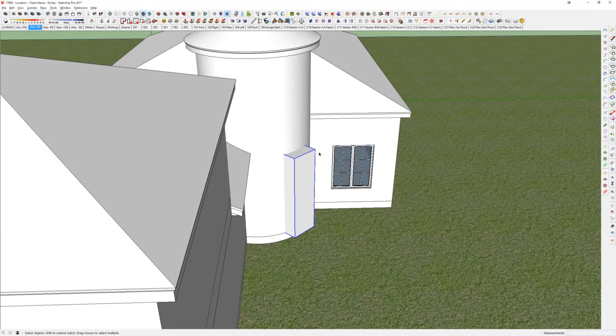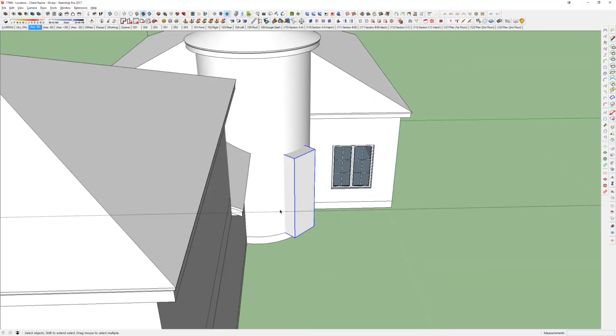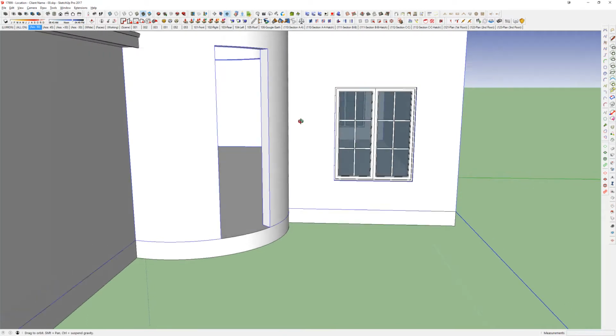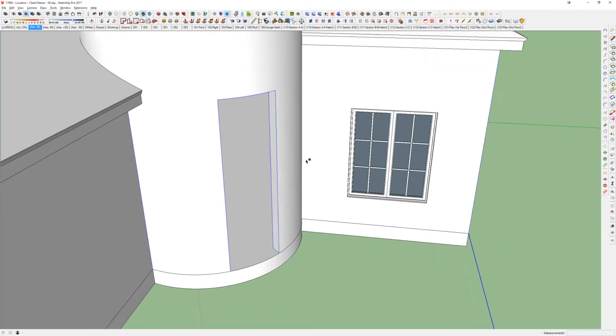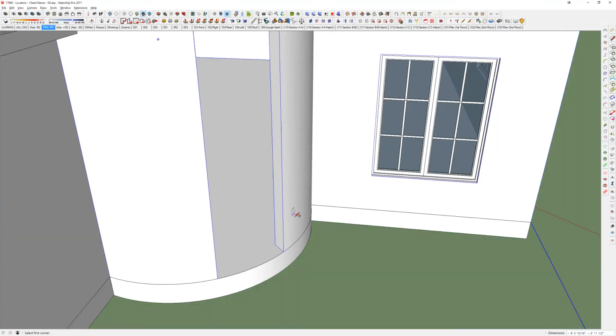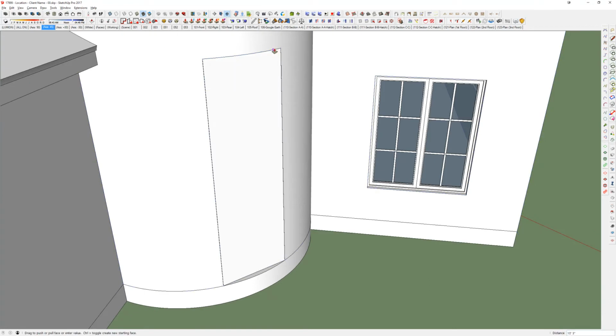But now I'm going to cut this just so I'm inside of my wall group. And now using my solid tools, I can subtract this out of here. And there's my opening for my front door. I don't have a door right now to throw into it. I'd have to open a file, and that's easy enough to do. But you get the point that now I can just put my door, it would basically sit there just like that.